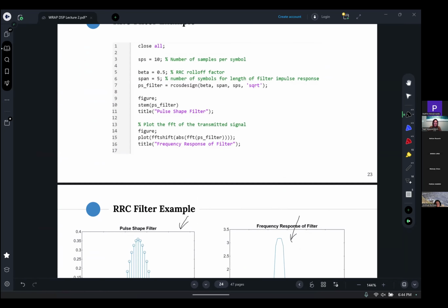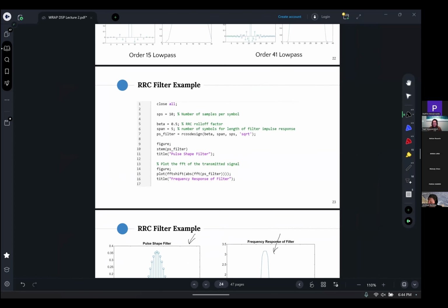Then we tested trying to get away with as low as 5, because the lower the order of the filters, the more computation we can save. So we are just trying to figure out the minimum amount of space for the filters that we need in order to optimize but have it still work. That's something that we played around with a lot in DSP R&D last year.